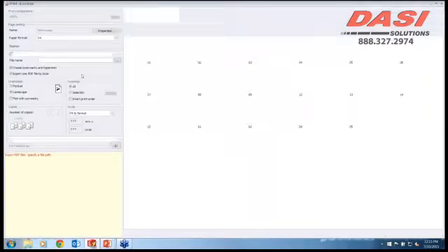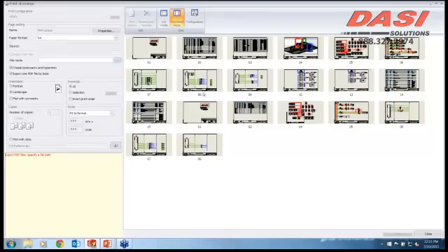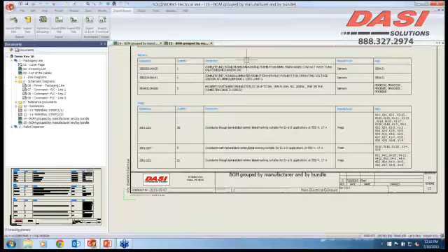You can also do things like exporting the PDF. Now here, exporting this PDF, if you remember those hyperlinks that we talked about before, you can add those hyperlinks into your export if you are exporting as one PDF. So therefore, you would be able to go ahead and click one link, and that one link would take you from sheet to sheet to sheet, especially like with your go-tos, your cross-references, any of those type are fully available in the PDF format. All right, and then of course you can export the entire thing. We also have some importing features which we can discuss at another time.